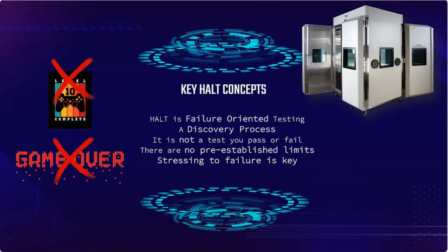Now, here are some of the key concepts behind HALT testing. You'll see that HALT is a very different kind of test from what you may be used to doing. If you're used to doing design verification testing or reliability growth testing, those obviously are tests that you have to pass, and there are very clear, established limits to the stresses that are applied during those tests, and you certainly expect to get through those tests without any failures happening.